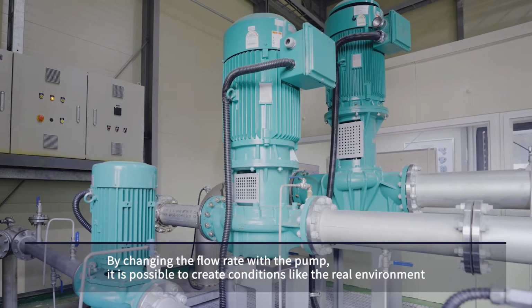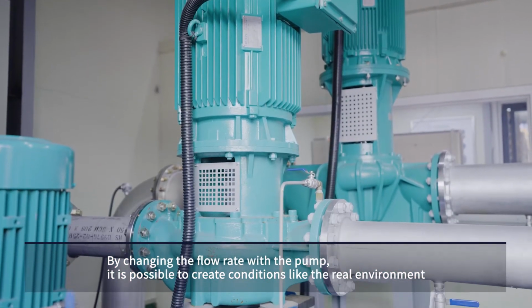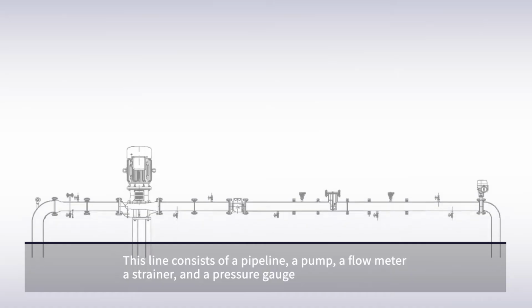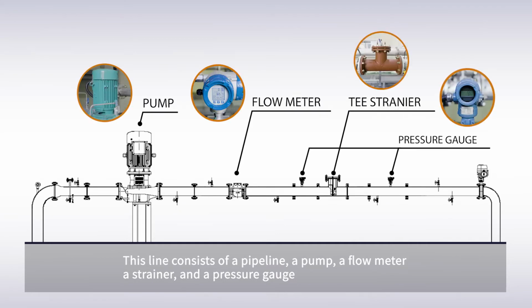By changing the flow rate with the pump, it is possible to create conditions like the real environment. Accordingly, it is possible to check the change value of the differential pressure in real time. This line consists of a pipeline, a pump, a flow meter, a strainer, and a pressure gauge.